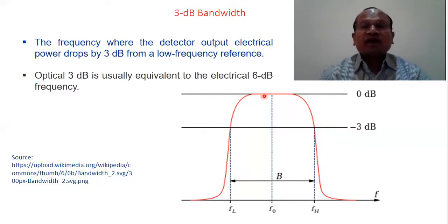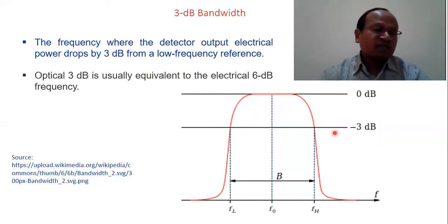Because when you find this value as a maximum value, and you find out the value of the amplitude or the gain at this frequency, I will tell you this becomes 1 upon square root 2, which is 0.707 times the maximum value. Now you remember, 0.707 times something is called RMS. So sometimes we speak of the RMS lower cutoff frequency, the RMS higher cutoff frequency, and the range is called bandwidth.